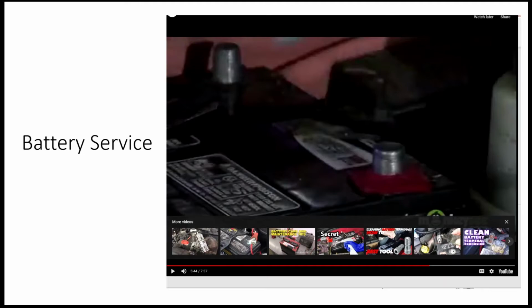The best thing to do is take some regular soap and water after you've neutralized all of the acid. Just some soap and water, like a wash mitt from a car that you wash your car with, that maybe you keep for just washing under the hood stuff, right? Clean the battery. And wash it off. Hose it off and let it all run out down the driveway or whatever you have to do. As long as it's been neutralized and completely eradicated, it's not a toxic product at that point. If it's been neutralized properly. Now, if it has not been neutralized, you can't just wash it out onto the ground. That's a toxic product.